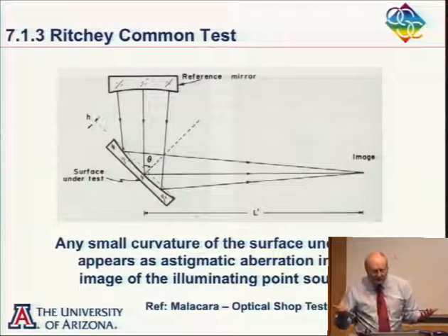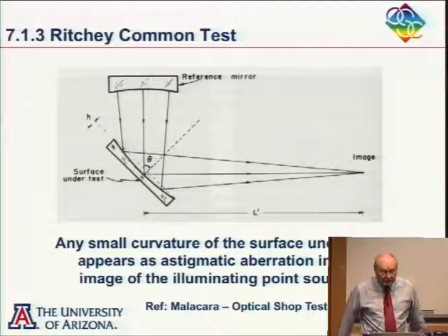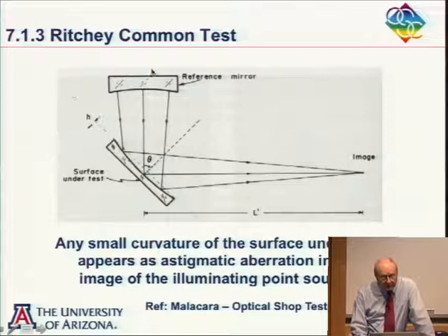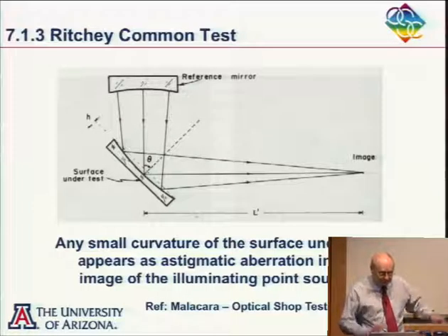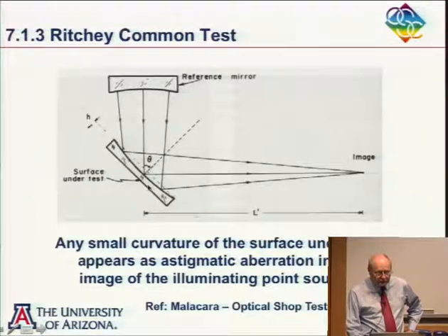And so you would measure the sphere. You have to have a good sphere. So if you're putting together your optic shop, you start off by getting a good sphere or making a good sphere. And then you use that in the test here. And of course, it's very easy to get astigmatism here by just mounting it wrong, or just a sag of it. If you don't have a good mount, it's very easy to get astigmatism.